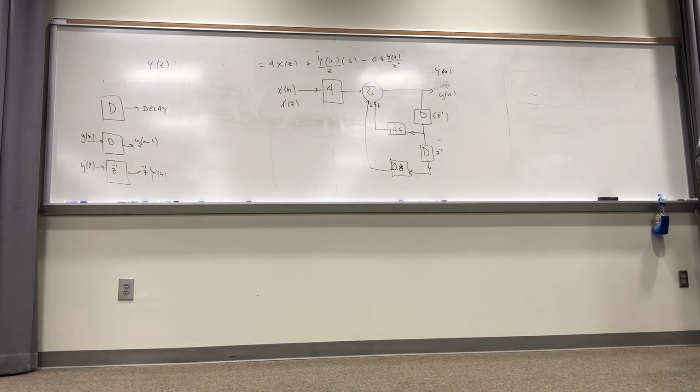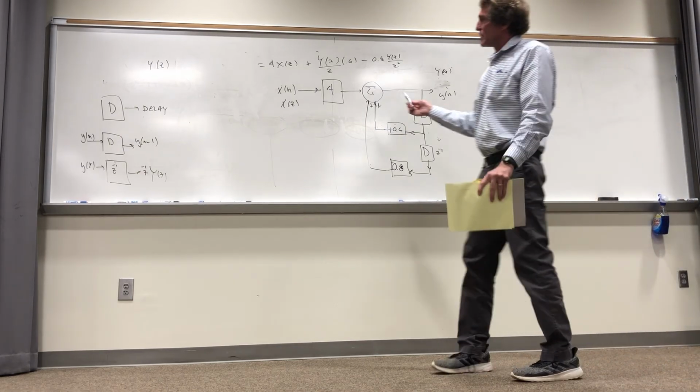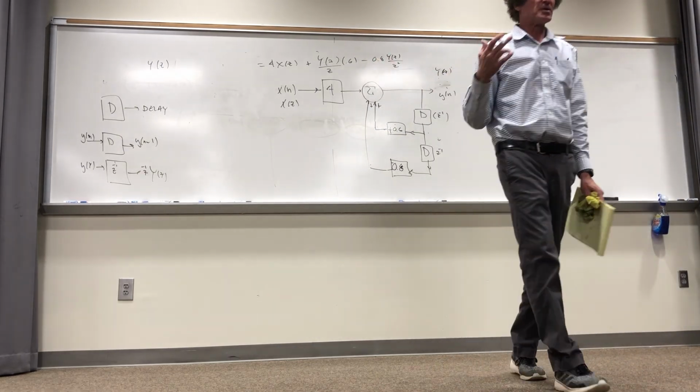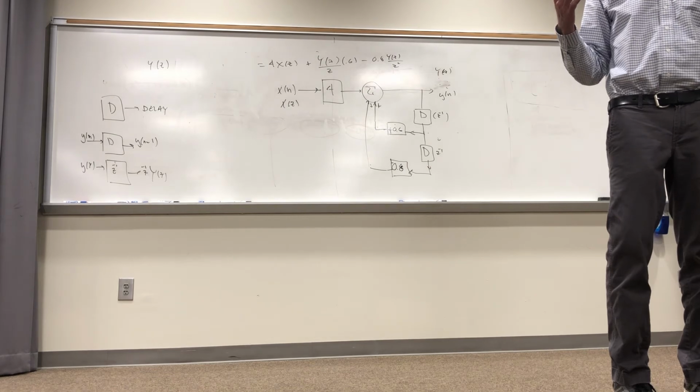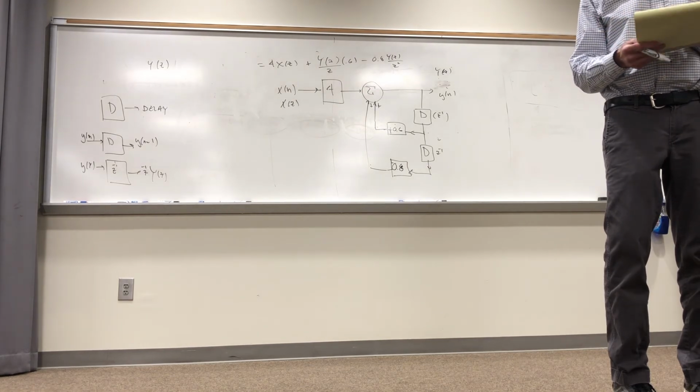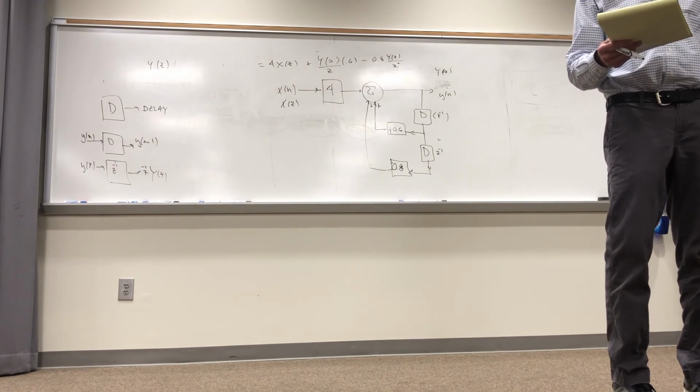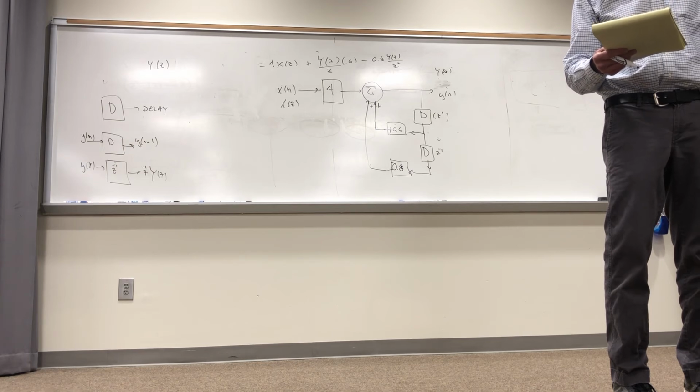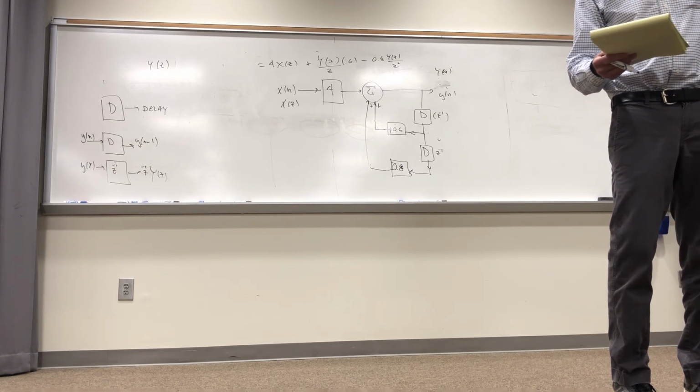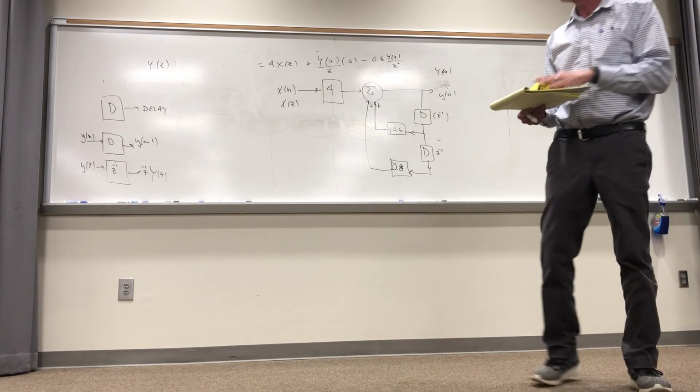Now, I want to tell you something about this. There's a lot of different ways to synthesize these circuits, or to actually show block diagram drawings. This is only one of many. One other thing I can tell you about for this one, y'all realize we could get a simple transfer function, h of z, right? And we could go ahead and we could break it into partial fractions, and we could get 2 separate circuits that we realize each one of those partial fractions, and then add summers to it. So there's many ways. This is one way, and it's commonly used.